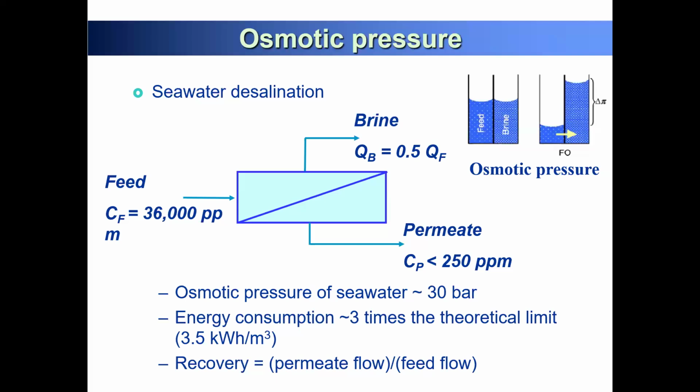So 28 bar, 35 bar, 40 bar, depending on that, I want to achieve 50% recovery rate. So your osmotic pressure is 40 bar. So you have to apply 80 bar pressure to achieve your overall 50% recovery. So this osmotic pressure will tell you how much pressure you apply, how much recovery you will get, and how much water you will receive.